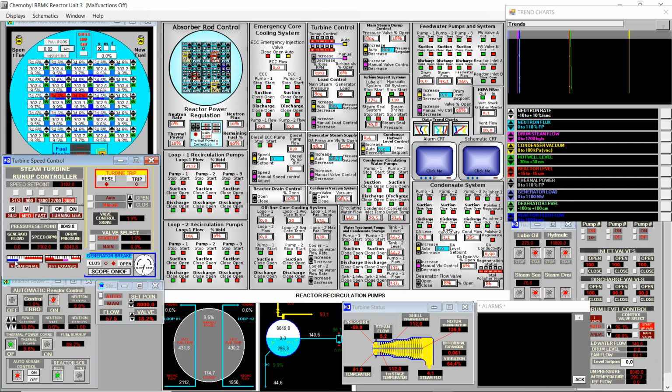The vibration is a bit high, but still in the acceptable range. And I will start decreasing a bit the power in the reactor. We could just keep at 10% the reactor while spinning down the turbine, because the main steam dump control relief valve is taking care of this, keeping the pressure in the drum constant, but this 18% of opening is just energy that we are wasting.